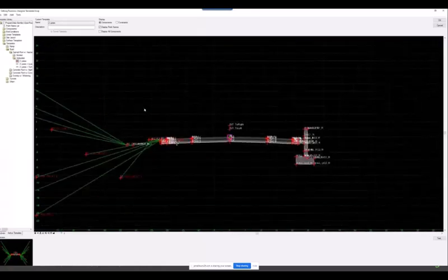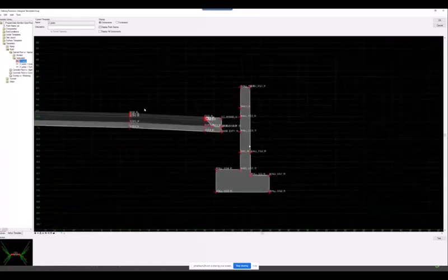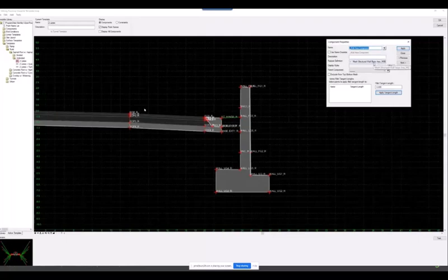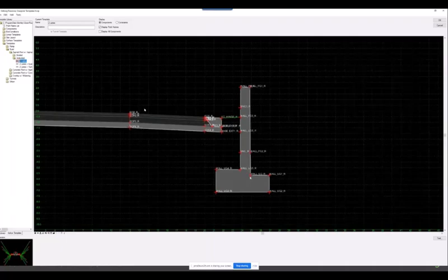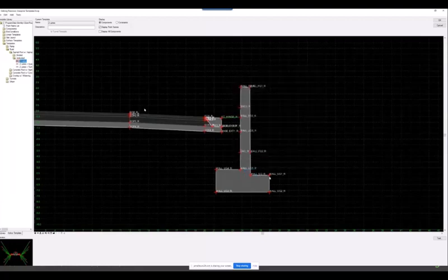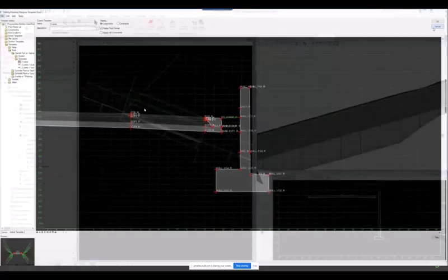So I could go in my template, and I'm just going to show you how to do this. I'm going to show that I have an extra component on here, wall area for the MSE wall, and I just draped it on top of the existing points that I had. That's fine, but there's a key to this. We keep a slope of, make sure we get it, 10,000%. This actually looks at things that are not sheer vertical, because obviously you look at the parallelograms representing the pavement, we don't want to show those also.